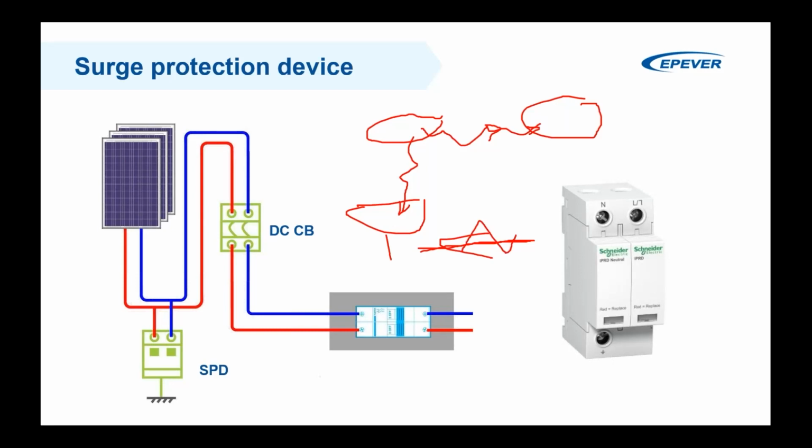So depending on the type of installation, it's better to have a surge protection device which guides the high current to the ground.